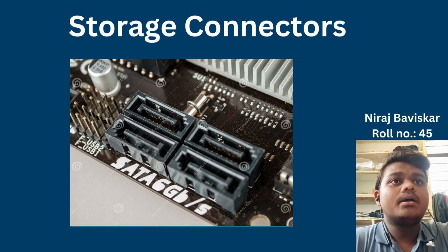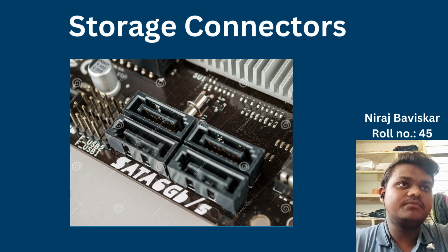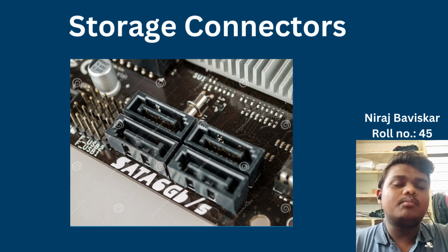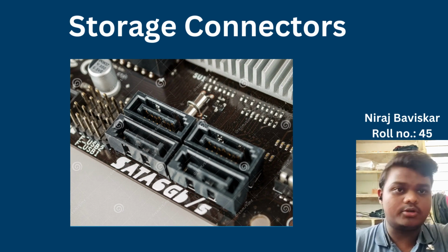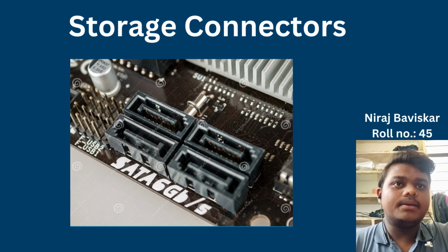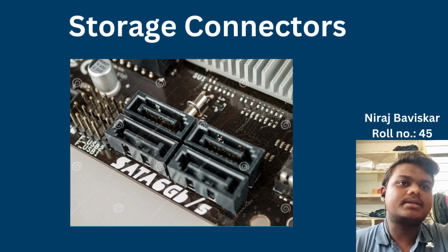Second, M.2 connectors, also known as next generation form factor connectors, represent a newer and more advanced storage interface found on motherboards. They have gained popularity due to their compact size and high-speed data transfer capabilities. M.2 connectors are smaller, resembling a small rectangular module or card slot on the motherboard. They support the NVMe protocol, which enables lightning fast data transfer rates compared to traditional SATA connectors. NVMe SSDs, when paired with M.2 connectors, can deliver significantly improved storage performance, reducing data access and transfer times.